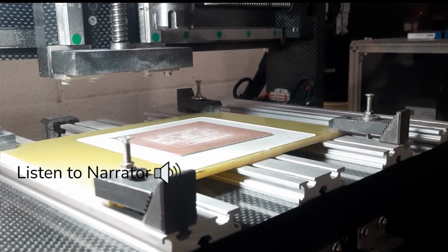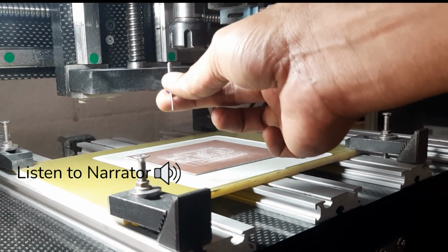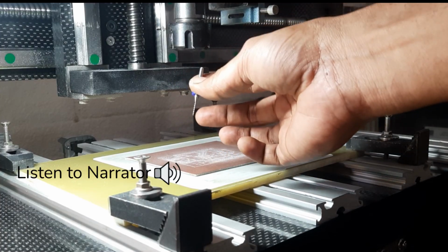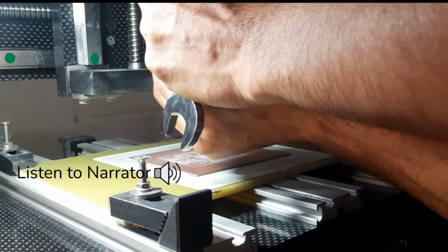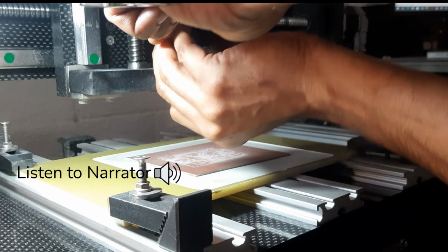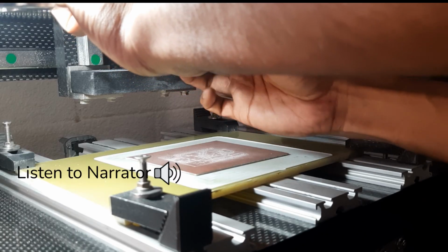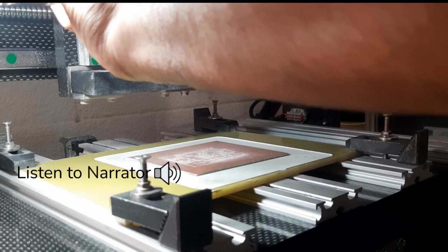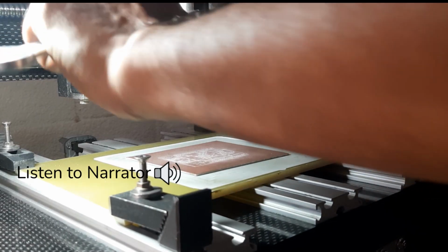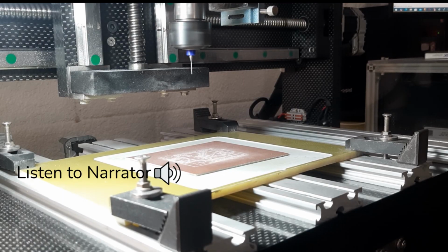The program will pause at tool change time, and the spindle will stop at a sufficient tool change height. At this point, we can insert the next tool, which is 0.7. The CNC job is loaded. We found the X, Y, and Z0 in this case.